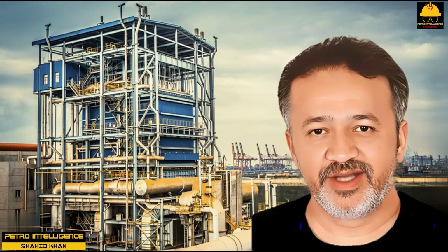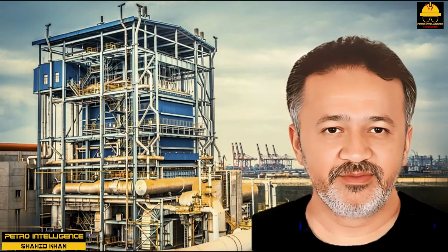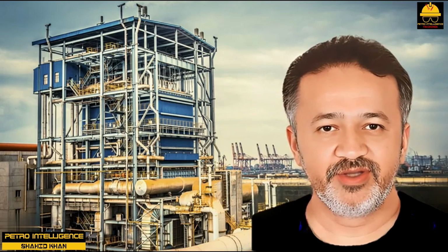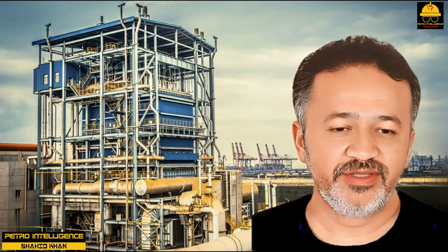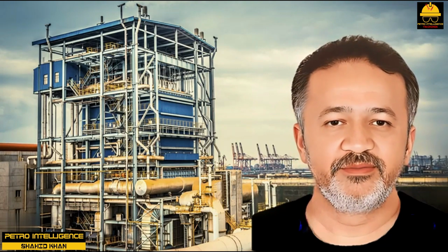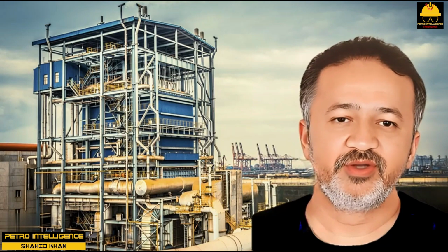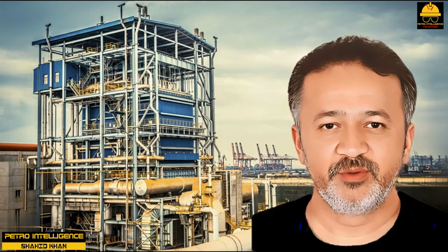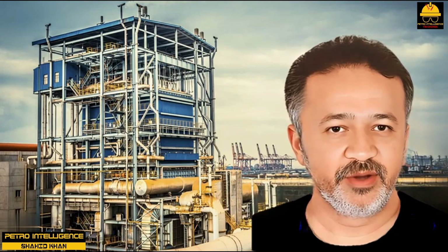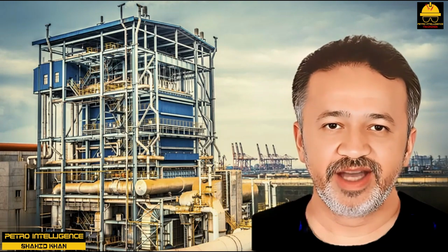In this service, the helical baffles seem to work well, resulting in less fouling, slower rate of increase in pressure drop, and better maintenance of heat transfer coefficient as compared to traditional shell and tube exchangers. These effects have proved consistent over several years. Another example from oil refineries is in crude preheat service with vacuum resid again on the shell side, with the helical baffles. Once again, similar results are seen as described above, with less fouling, reduced rate of increase in pressure drop, and better maintenance of heat transfer coefficient as compared to the conventional shell and tube exchanger design.